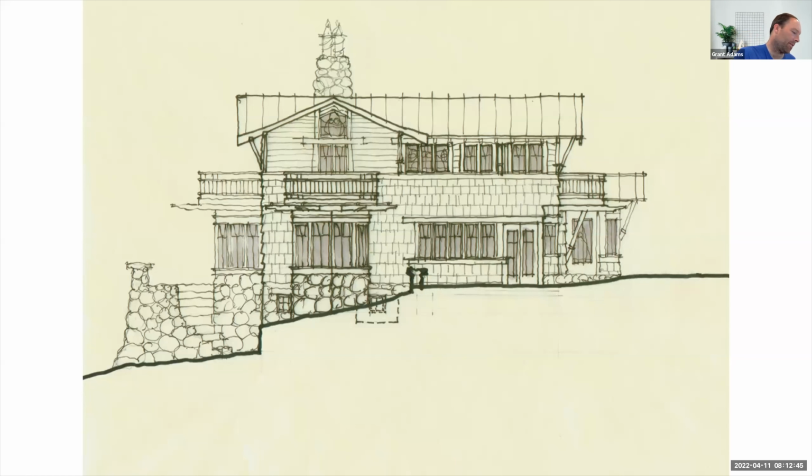The thickest line of all of it is this big bold line that goes all the way along the bottom. And what that is representing is where the ground is. So as we take this elevation, we've gone right up close to the building and we've cut a plane. That's our drawing plane. It's nice and tight to the building. And that's representing where the ground is and then what we're seeing behind it. So the thickest line is always what we've cut through, and that's the ground, and it's represented here.